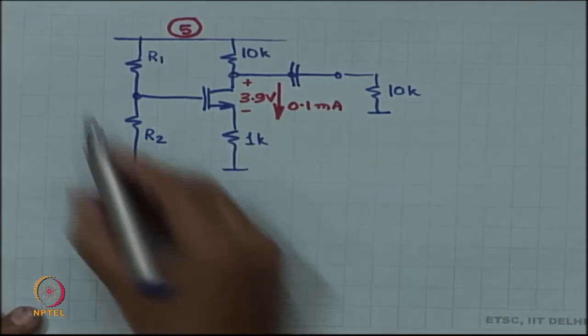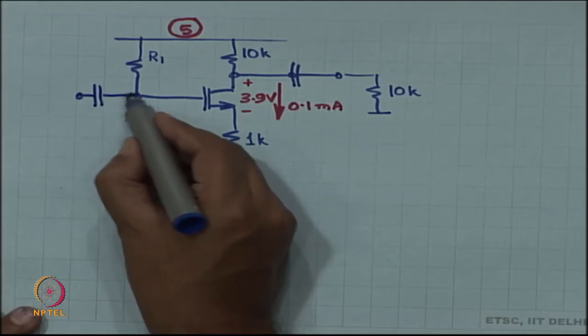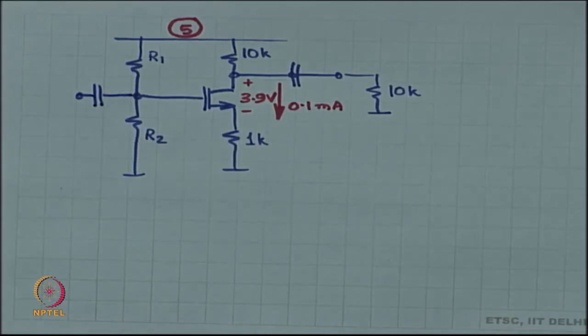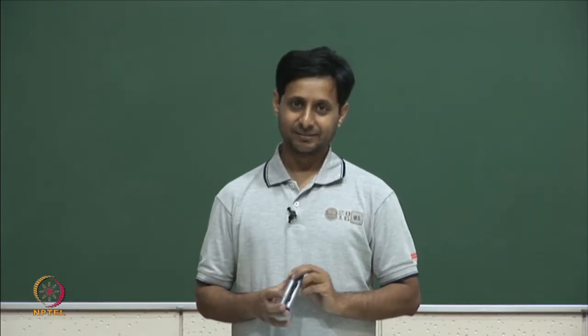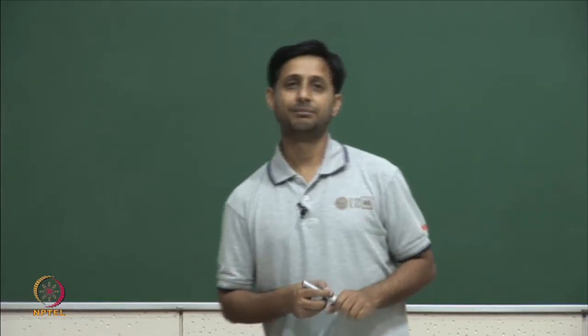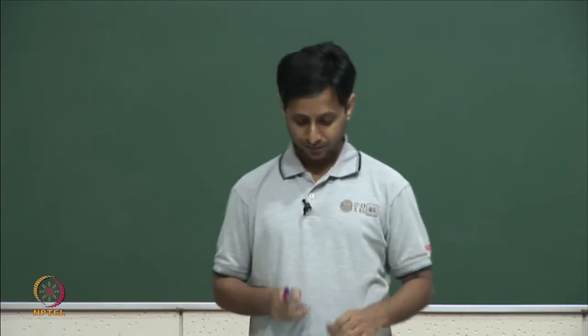What is the voltage gain of this circuit? Do you know? This is the source degenerated amplifier. Yesterday in the last class we had looked at the expression for this source degenerated amplifier. The expression was quite complicated, but when you say that gm is very large and gds is very small, strange things happen, a lot of things disappear, and finally you end up with the gain as minus RD by RS. Okay. So, how do you figure that out?